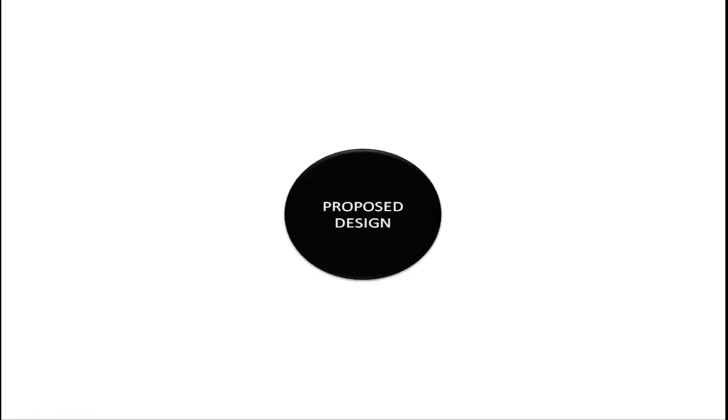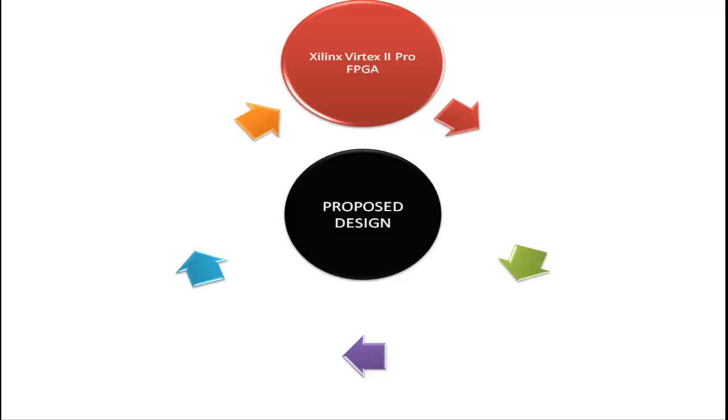First, we have to think about the design of the FPGA itself, and here is the proposed design. A Xilinx Virtex-2 Pro FPGA is selected as the autopilot primary processing platform, and these processors deliver DSP capability and can operate with clock frequencies that can exceed 300 MHz while operating in parallel with the FPGA logic slices.